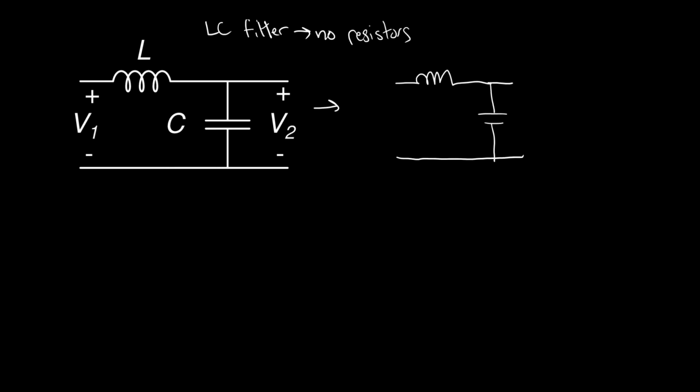those of you who do not, what we can do is convert this into the phasor domain, right? We can think of phasors as frequency-dependent signals, or we've removed the frequency dependence of these signals, so they're kind of constant over certain frequencies, but these elements, L turns into j omega L, and C turns into 1 over j omega C, and these are the impedances of these components, right?